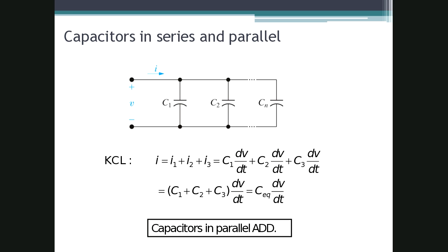Okay, so I'm going to go over a couple more things, which some of you already know, but again, I just want to review this. Whenever we're adding capacitors in parallel, we use the same phenomenon that we found with resistors and inductors that are in series. So basically, C total is equal to C1 plus C2 plus dot dot dot C to the n. So in this case, I'll give you just a quick example, and I think I did this already in a different lecture.